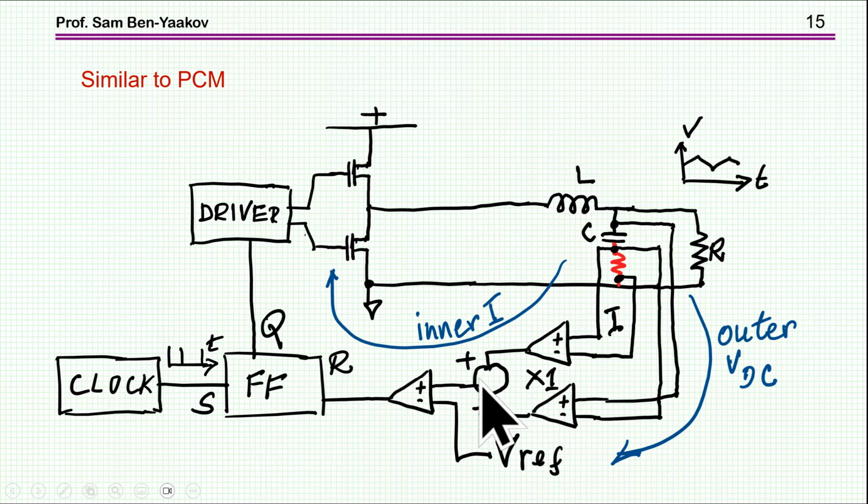And then if there is an error, it will start growing or going one way or another, and eventually it will stabilize to 0 here with the voltage of the sense equal to 1, and then of course we are going to get the 5 volt at the output.